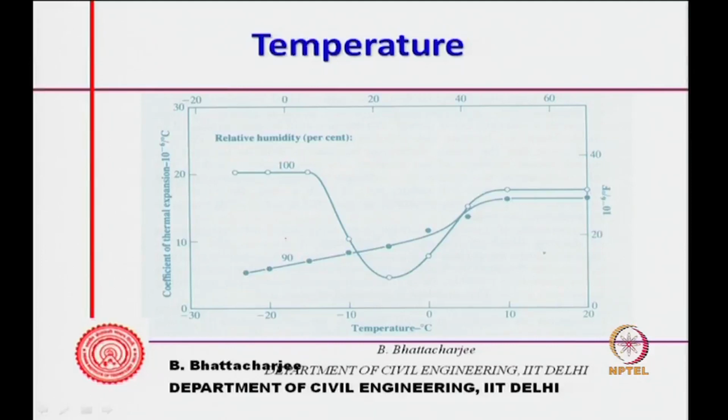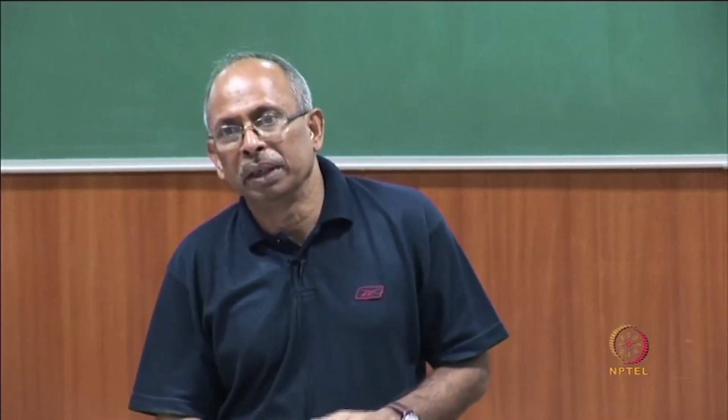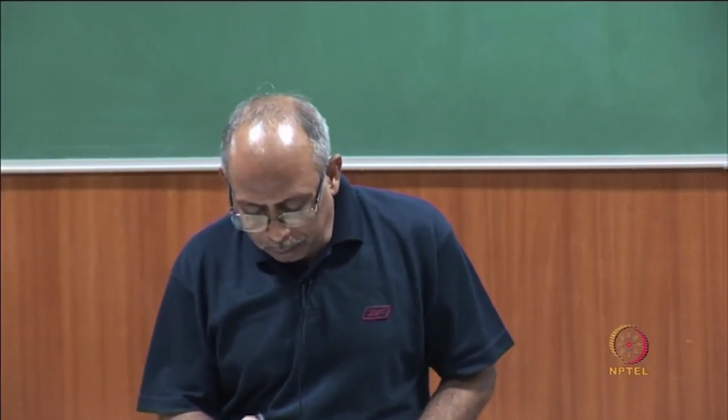There are some observed experimental results. At relative humidity 100%, the coefficient of expansion is something of this kind, and of course, it depends on temperature, at low temperature like -20. Now, more or less water will be mobile in this, although the properties of gel water are different. It is not the same as free water. It will not be like free water getting frozen. This may not get frozen at all, but properties are different.